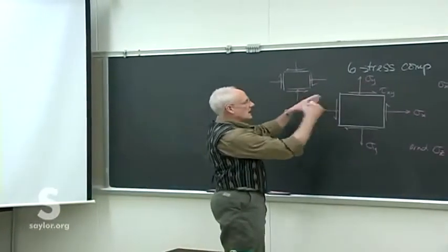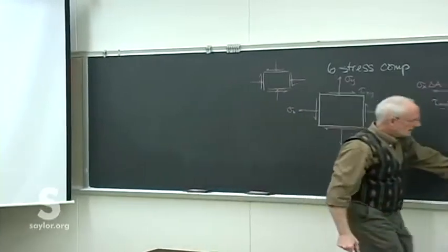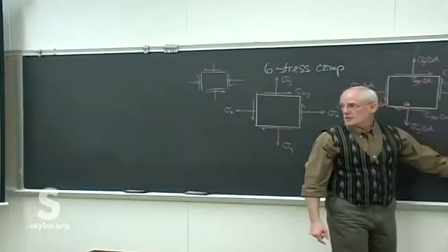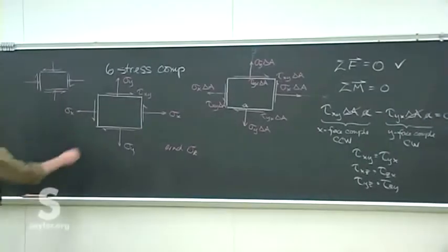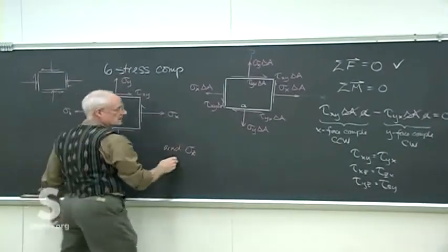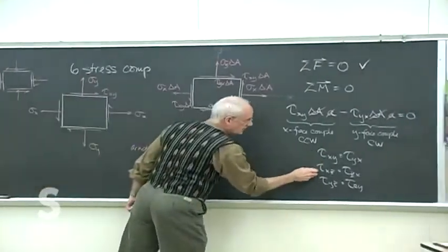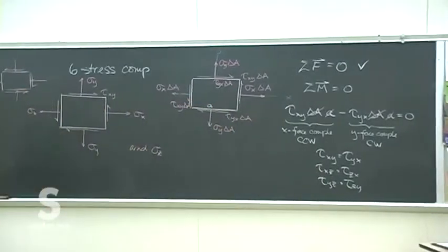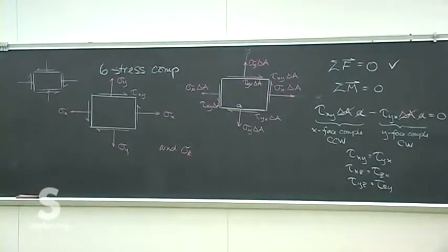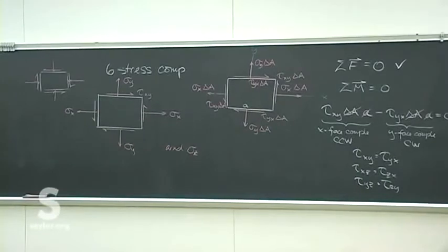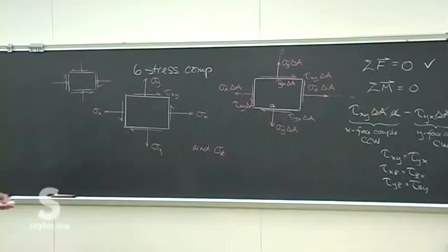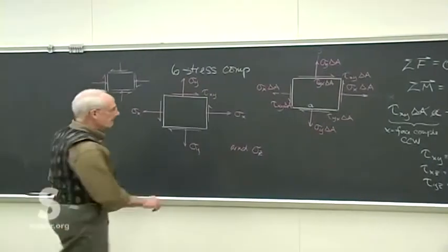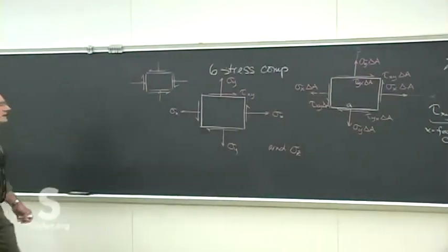If we happen to look at any of the other 2 directions, we just take into account the other 2 possibilities for the shear stress. So that's 6 components: 3 normal stresses and the 3 possible shear stresses. We're down now to just 6 stress components for an entire 3D analysis of the stress on a structural member.